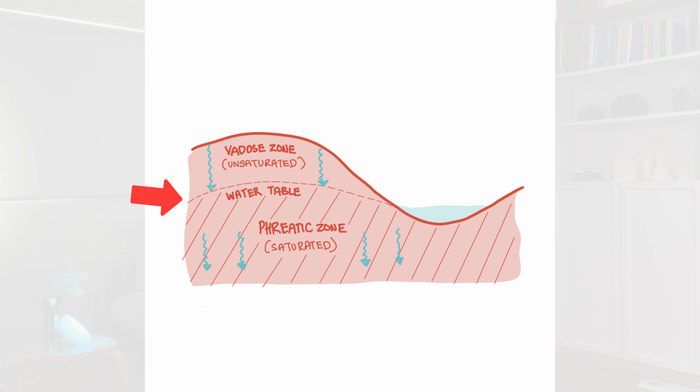The unsaturated zone is often neglected because it is assumed that the water table level is the only thing to worry about. And the water table line is not always static. It can also rise and drop a few meters depending on conditions. If a geotechnical engineer defines that there is substantial groundwater present, a hydrogeologist should be engaged.